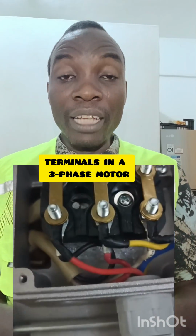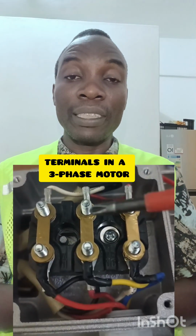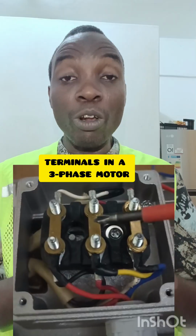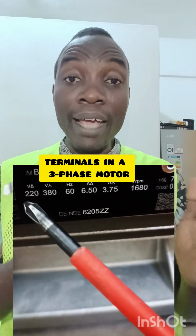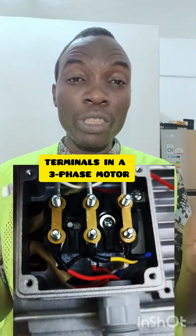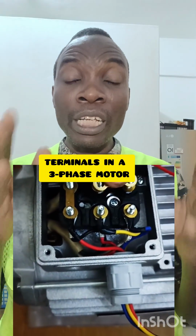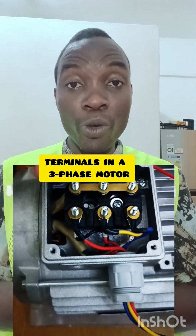A three-phase electric motor has six terminals. And these six terminals can be manipulated in different ways in order to run your electric motor. You can manipulate them either in star form or in delta form, which means you just need to interconnect them such that it will give you either a star or a delta configuration.